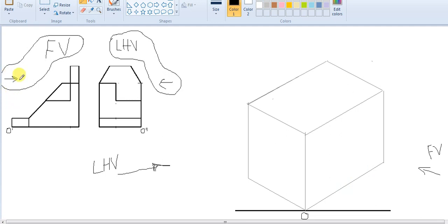So when you are looking from this side at the extreme end, we'll be able to see a flat surface. Now the shape of the flat surface is somewhat like this. So there is a flat surface and then it is tilting down. Now this particular region, let us divide. As you can see, I have tried to divide it into different layers, so that this A layer and this A layer, they are the same. So in short, the length of layer A will be obtained from this view. However, the width will be obtained from this view, and the heights are same. That is how it goes.